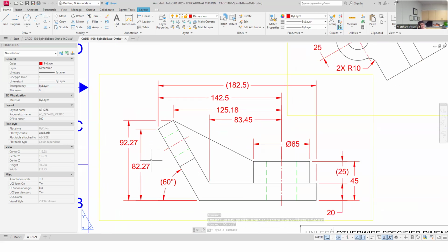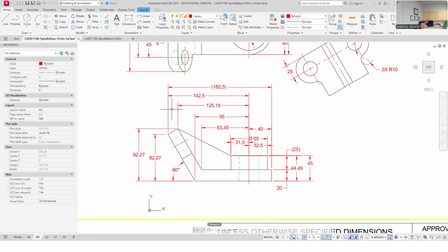No, technically you don't. That's why I've got it as a reference for sure. Yes, I feel like in some industries, I would drop these X and Y's and put in actual lengths, and they would be aligned dimensions on here. And that would be okay for a lot of industries. So that's where I come in to say, just be flexible on that and know that X and Y is like ASME, but other industries might break that.